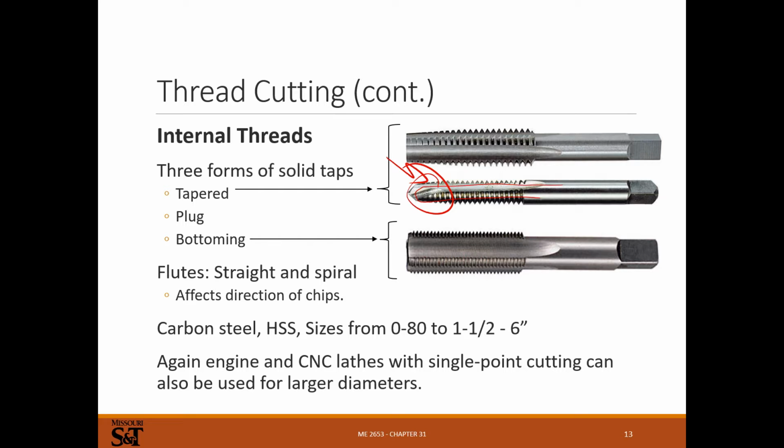They make taps from small to large. At some point, this is a pretty safe operation. Usually once you get past 1/4 to 5/16 taps, it's pretty reliable and you don't break them. When you're trying to tap small, like a 10-32 hole, in something really hard like 4340 steel or some stainless steels that work harden badly, this can be a nightmare.